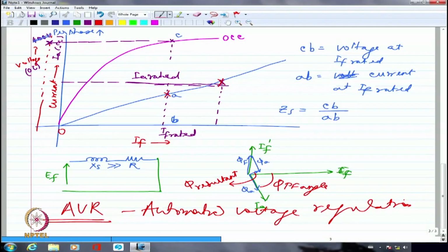The field is only working as a via media. It's a facilitator. It is definitely not giving any resources. It is only a facilitator. So, you can't really take the field current as the current which would reflect on the impedance of the armature. That's not possible. The same way, in the short circuit condition, obviously the voltage that I would measure across the terminals of the armature will be zero because I have short circuited. So, I don't have a way to measure the armature voltage.